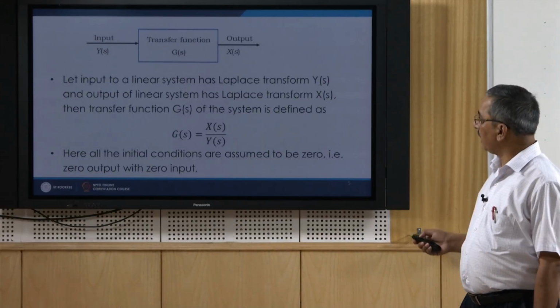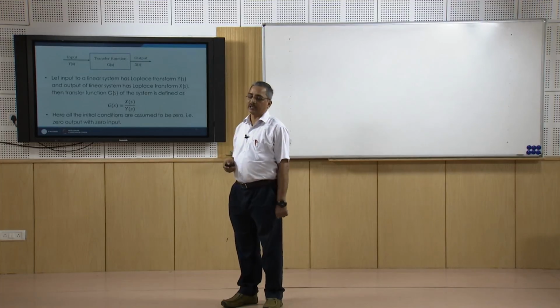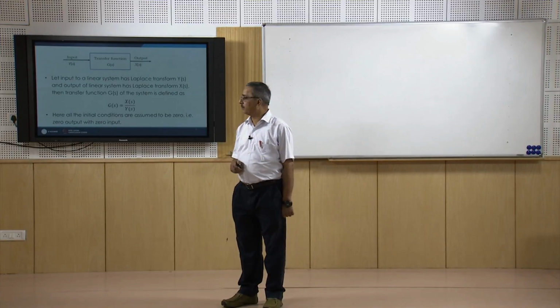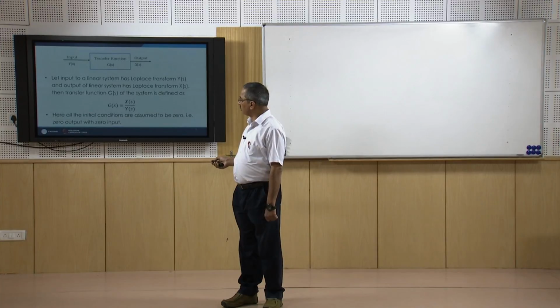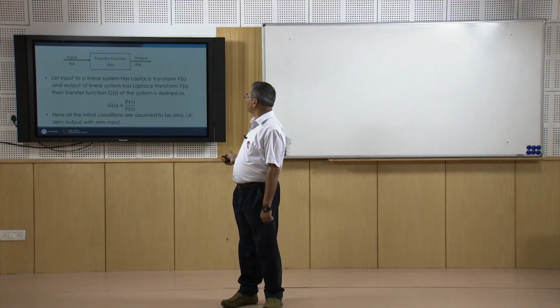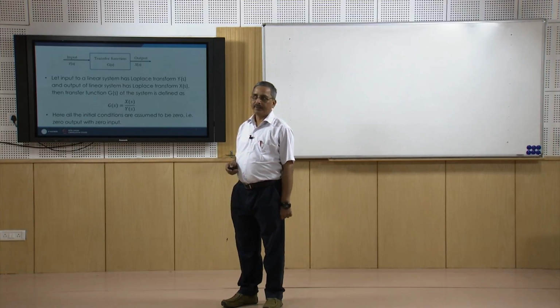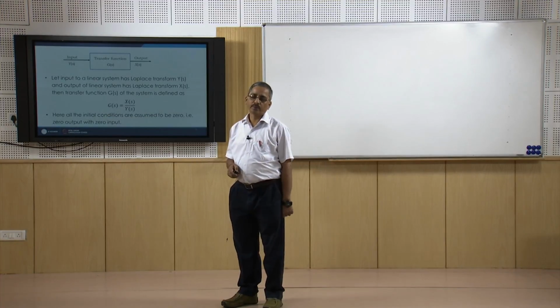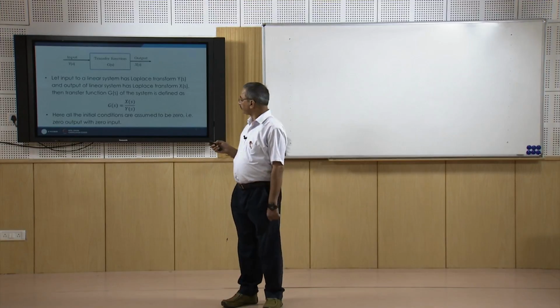And of course, when we are defining the transfer function, one thing we always need to keep in mind is that we are assuming all the initial conditions to be 0. That is, the 0 output with 0 input condition.